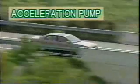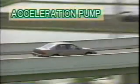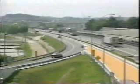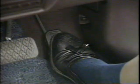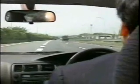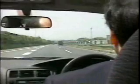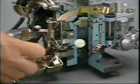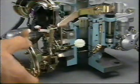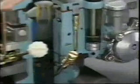Now let's take a look at the acceleration pump. We all know that to achieve quick acceleration, the driver needs to depress the accelerator pedal suddenly. The acceleration circuit is designed to prevent engine hesitation during such sudden acceleration. With the pump-type acceleration circuit, when the throttle valve is suddenly opened, the pump lever depresses the pump plunger.